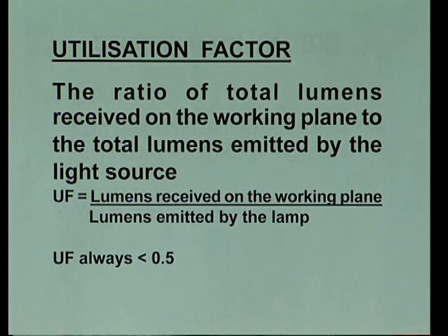So, considering all these factors, the utilization factor will always be less than 1, because due to wastage, the light emitted by the lamp cannot be utilized by the working plane completely. Therefore, the utilization factor will always be less than 1, and it varies from 0.3 to 0.5.